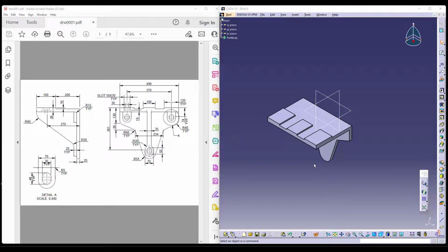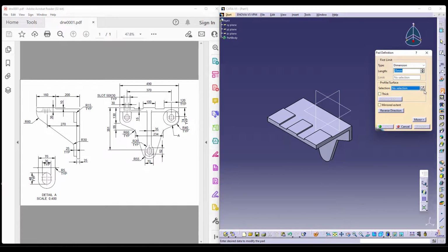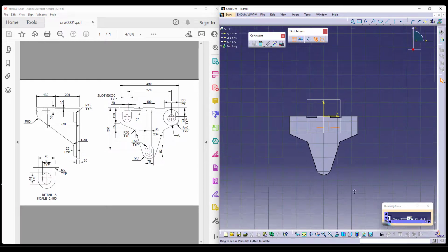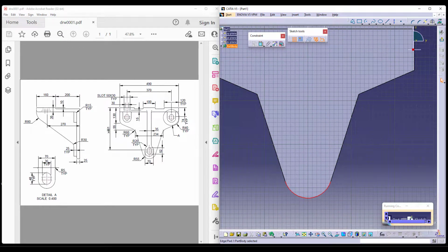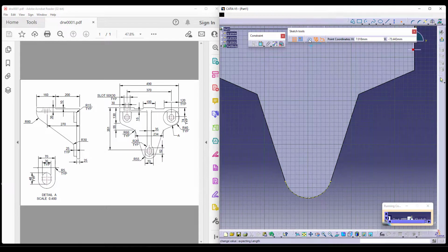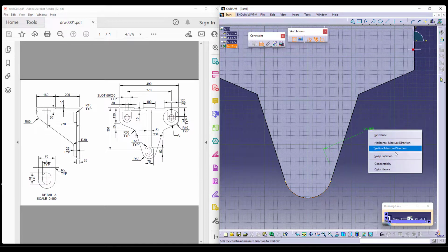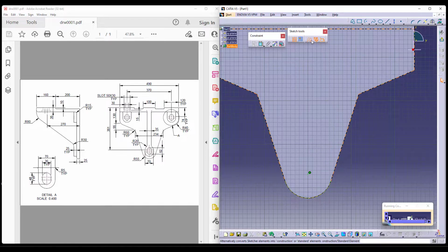Continuing the model, to make this rib, we require this feature. This feature actually has separate dimensions as well. So let us try to make that feature on the reference. This is my reference. On this, I'd like to make it. We already know that this center is the center of the internal slot second point, which is none other than 351. Again, I'm trying to use this as a reference. Now, while placing a point, I'll try to maintain concentricity with this. So I will get the initial point of my slot. This is the initial point of my slot.